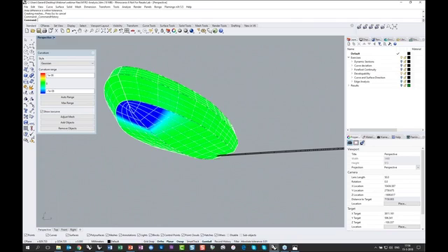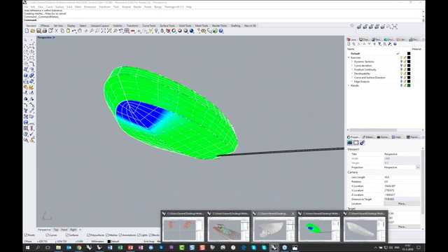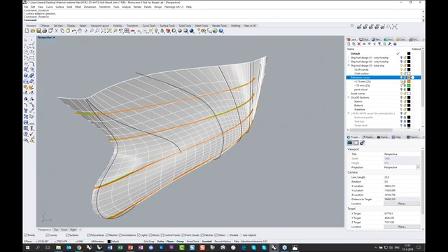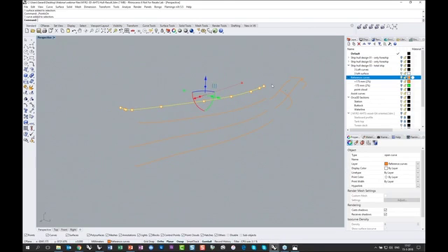Another question from Peter Forsane is, do you have a simple way of making a hull of a laser scanning? Well, actually, that's the same that I have done over here. But then, what you need to do is to create these curves based on the laser scan. So then you create in a laser scan curves that are exactly on top of your points, and then you create the reference ribs on top of that.